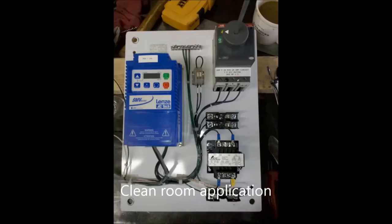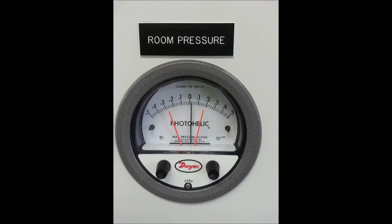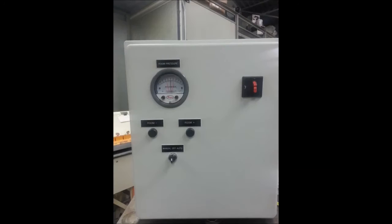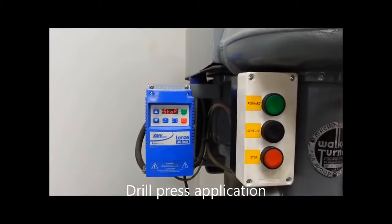Now here's a unit that we use, same controller, and it just goes inside of a cabinet here. And this unit is controlling a blower motor via a Photohelic. We use speed reference, high and low switchgear to ramp a motor up and down to maintain positive pressure in a laboratory clean room environment. You guys have probably already seen this. I run that off to the side.